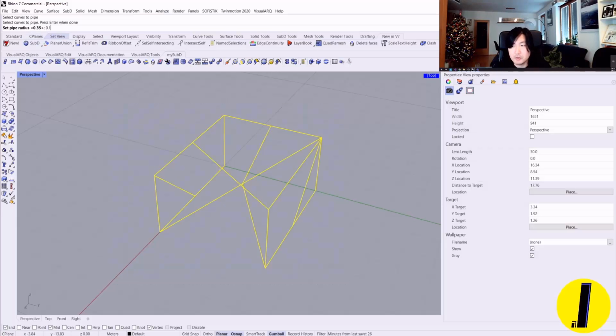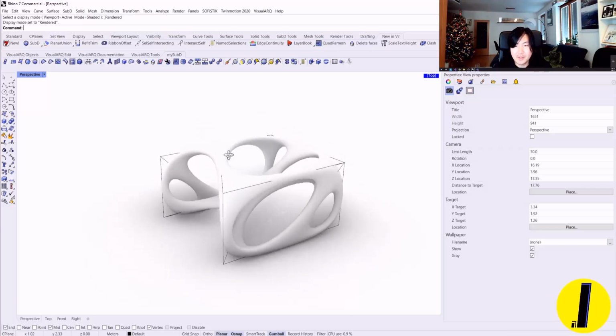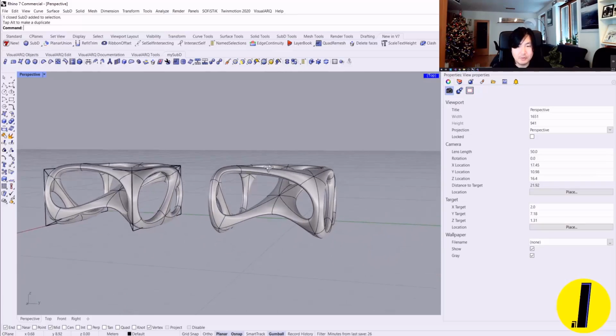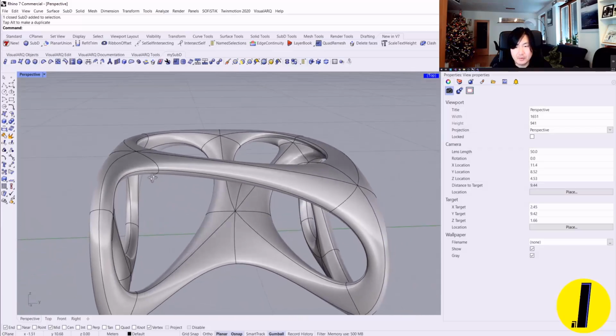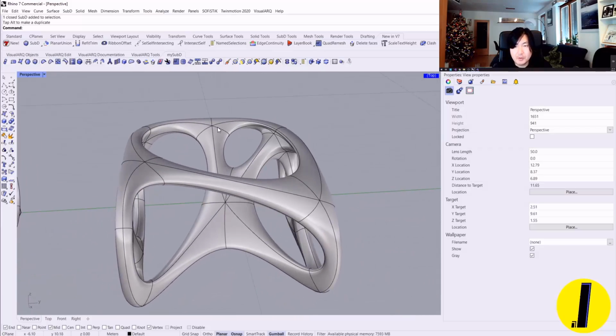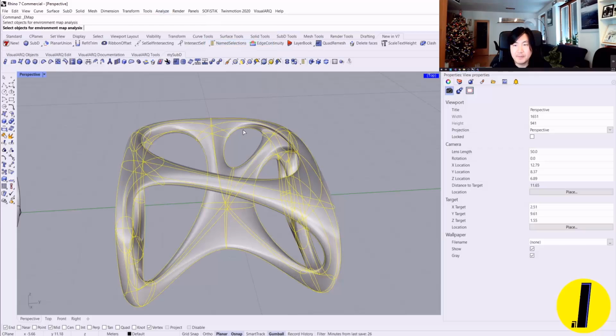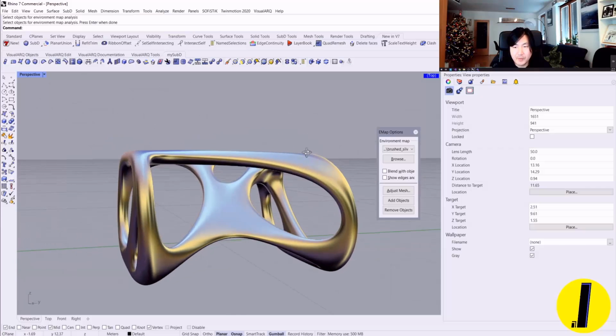Same. Let me make it to 1.15 centimeter radius. Keep the same setting and make it smooth. Hey, have a look. This is awesome, because previously with just the normal pipe tool, it was impossible to create this sort of organic geometry. So if you turn on your environmental map, we can go to analyze surface and environmental map, and I select this one, and you can see this curvature keeping.